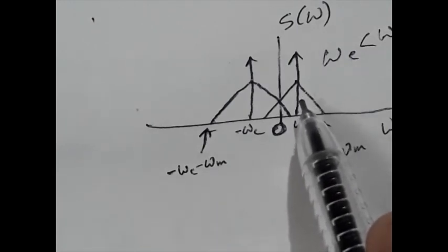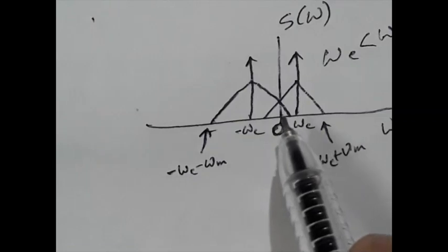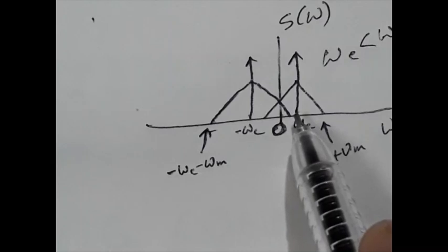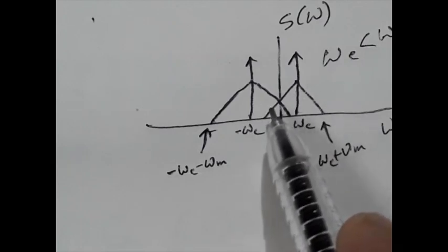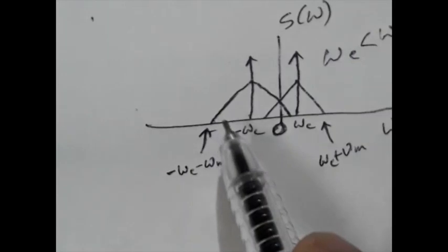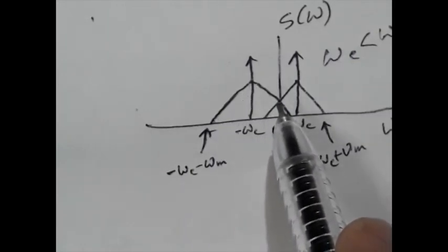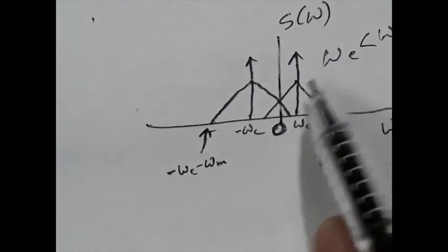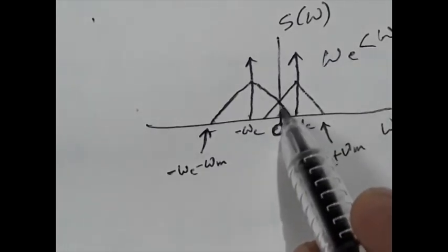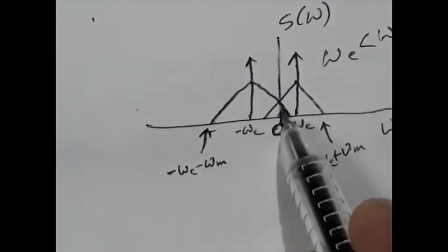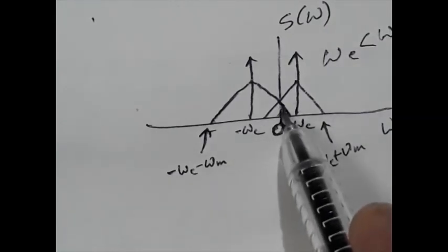The figure will be identical with the previous one. The only thing is that omega c is much closer to zero frequency. So what happens, this lower sideband is going to the negative frequency part, and a portion of the negative frequency part of the spectrum is coming to the positive part, this section. So there is an overlap,